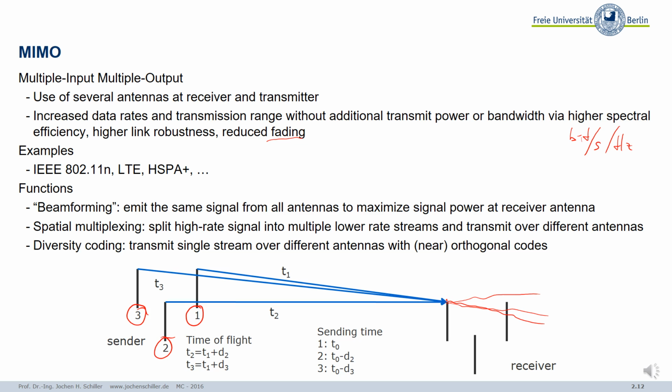And this is all handled in an electronic way, so you do not actually have to move someone with your antenna. That has been done many years ago. Maybe you saw some of these old applications, or military applications, where you had to follow with your antenna, and today you do this in an electronic way. So you can actually move your beam in an electronic way by changing the phase, by delaying more or less your signal. This is how you form your beam. So that is used, and that's more or less the most enhanced way of using your MIMO technology.